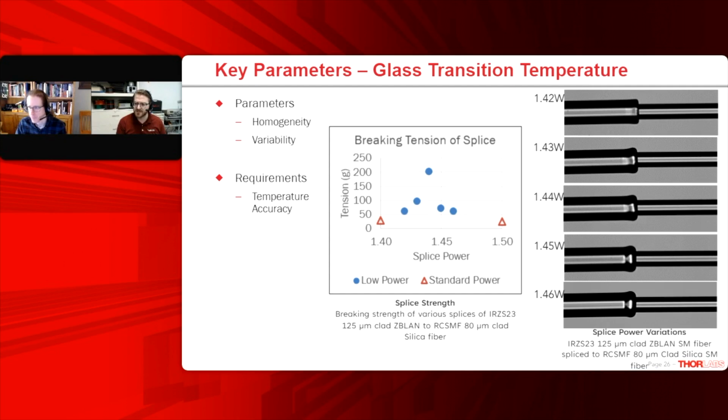I usually balance at the top of every day just because it is a mechanical system and you want to make sure that everything is in the same position. I think your mechanical tolerances are going to be looser than the thermal or optical tolerances at that point. But it should be a very similar splice file from one day to the next with the same lot of fiber. Got it. Okay. And actually, as we were answering that question, we had a follow-up come in.